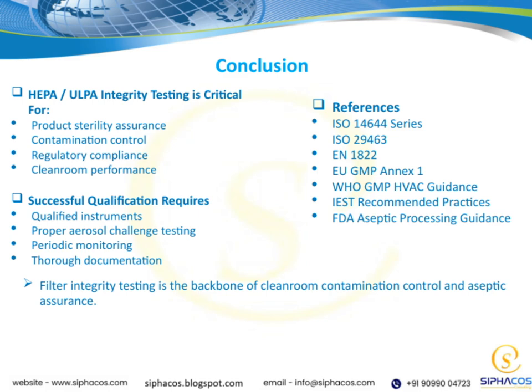All of these emphasize the importance of verifying that HEPA and ULPA filters are functioning properly. When we talk about HEPA or ULPA integrity testing, what we're really focusing on is ensuring product sterility, controlling contamination, maintaining regulatory compliance, and achieving optimal cleanroom performance. If these filters aren't tested correctly, the entire contamination control system could be compromised.